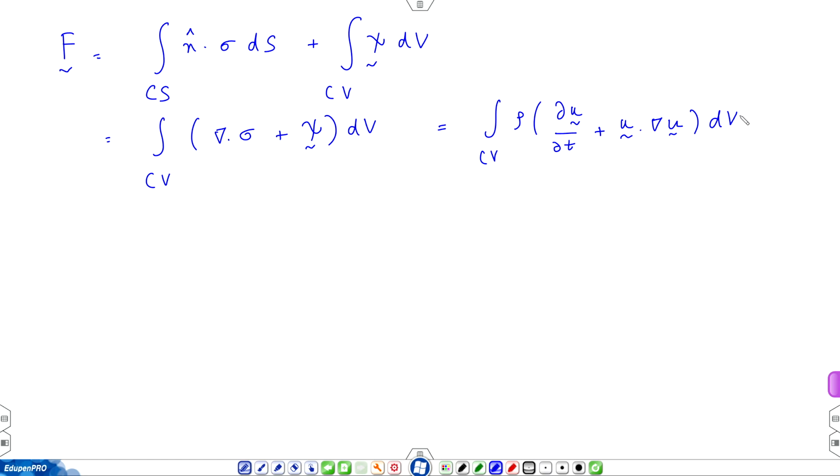See, we are not saying anything new. Left hand side is surface forces plus body forces, sum of all external forces equal to mass times acceleration. So, the same story continues in a different form. This form is useful in coming up with a local description of the flow field. Why local? This is still C_V. Now, the choice of C_V is still unspecified. You may shrink it to a point or just drop it.